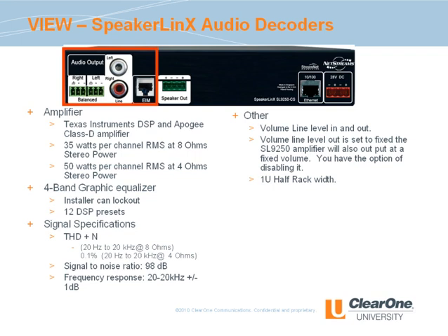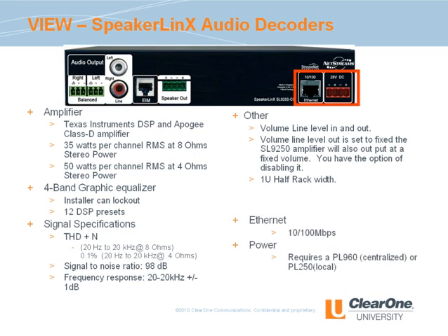The SL9250 is built into a half-rack 1U high chassis, which allows 2 units to fit into a 1U rack slot. Of course, like any View device, it requires a connection to the switch and it needs power. Notice that the SpeakerLinks has a 4-pin power module. You will want to make sure that you wire all 4 pins.